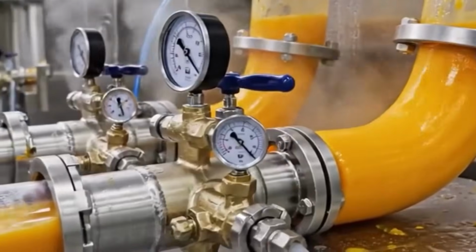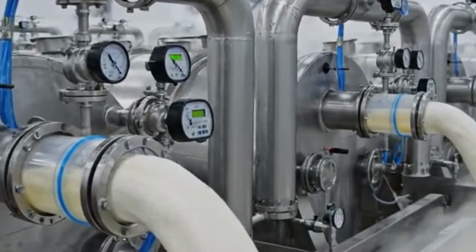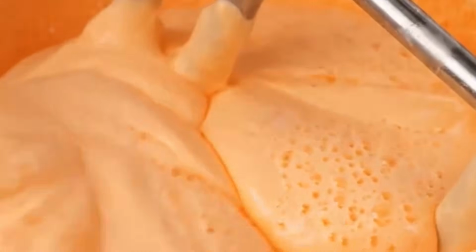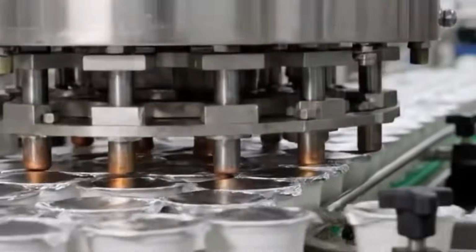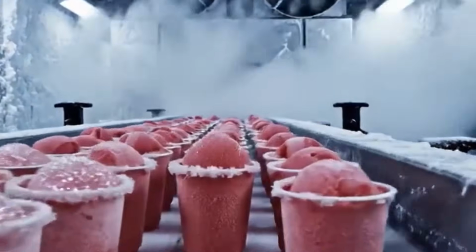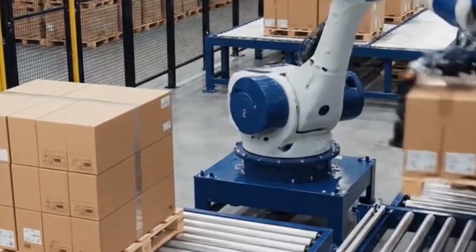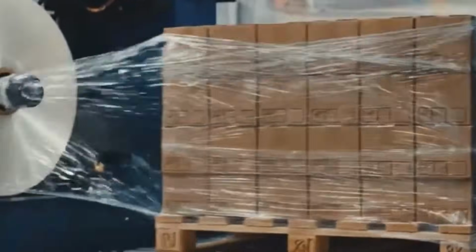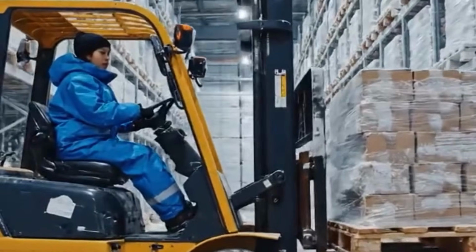Following pasteurization, the mix is rapidly cooled to 4 degrees Celsius using chilled glycol in the final section of the exchanger. It is then pumped to aging tanks, insulated, vertical stainless steel silos with gentle agitators. The mix is held for 4 to 24 hours, depending on stabilizer type, allowing the hydration of hydrocolloids and maturation of flavor. During aging, key metrics including Brix, viscosity, pH, and color are measured at regular intervals using inline and lab-based sampling.